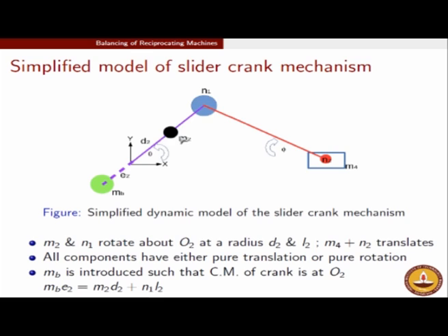The crank mass which is rotating can be lumped exactly at its own center of mass. So now you have the center of mass of this system exactly at the hinge point. Therefore there is no unbalance left in terms of the rotating masses of your IC engine. Remember, in the IC engine there are rotating components like the crank, and there is also a reciprocating component. So the unbalance due to rotary components at this stage has been killed. The unbalance due to reciprocating mass still remains.